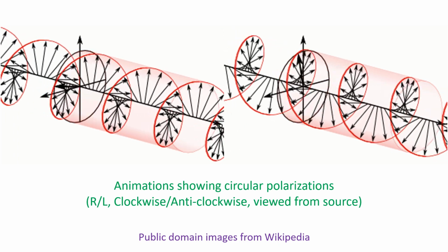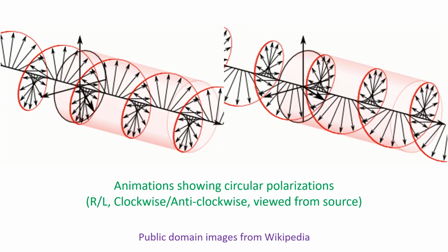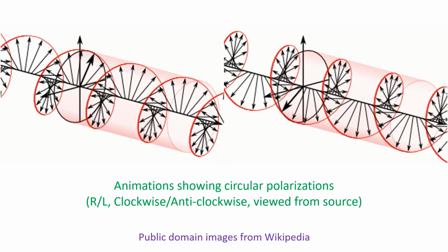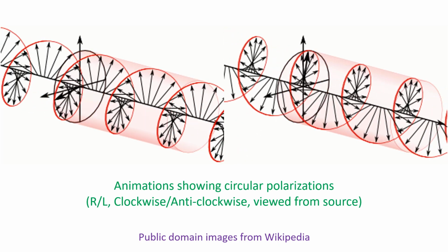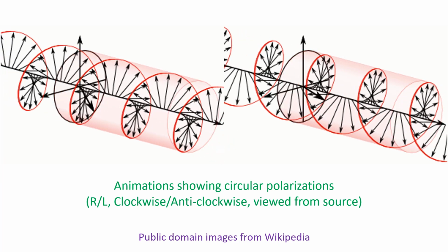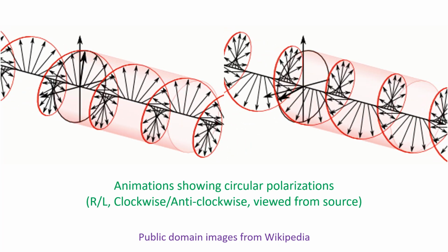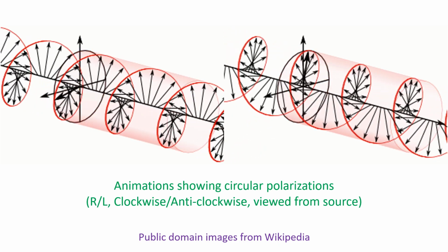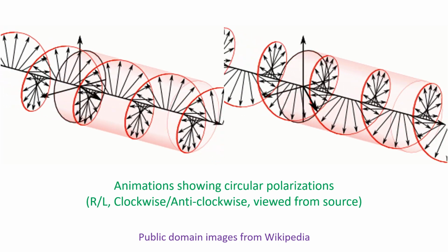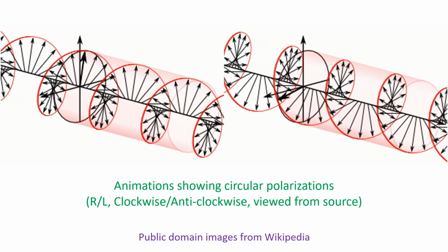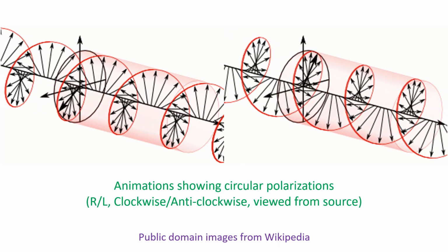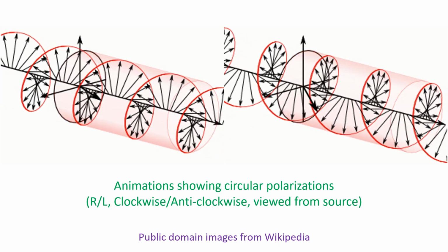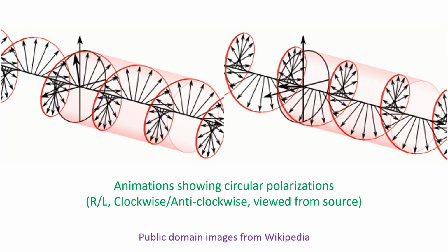Circular polarization is achieved by having two Yagi-Uda antennas built on the same boom with elements perpendicular to each other and fed by a phasing section of cable. If the phasing and dimensions of the elements are not accurate, it will end up as an elliptically polarized antenna instead of a circularly polarized one.